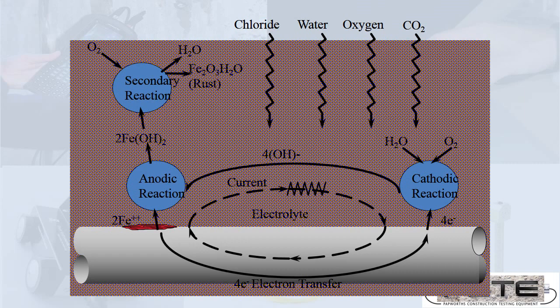When you place steel in a very basic environment like concrete, it forms a protective layer of oxide, and this needs to break down. Then corrosion can occur. Typically this is going to be in marine environments, ingress of chlorides from salt water or similar, or it's going to be in areas away from the ocean, or in carbon dioxide rich areas such as road tunnels. It may be that carbonation is the aggressive chemical coming in. This is a real 5-second overview. It's just important to understand that this is what we're mapping when we talk about some of the non-destructive tests.